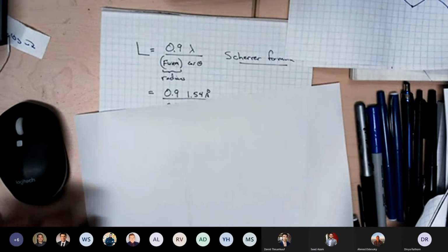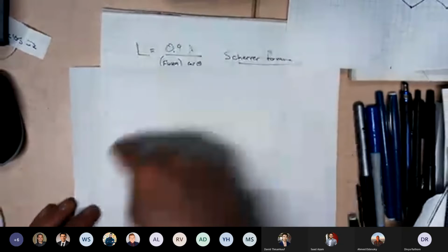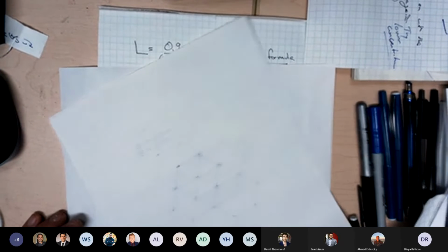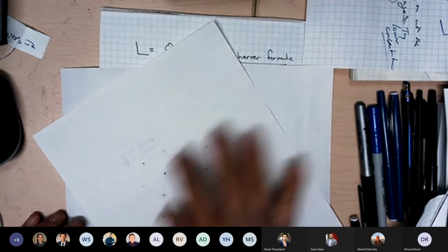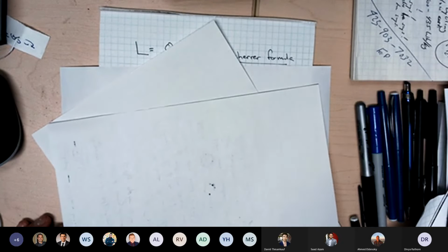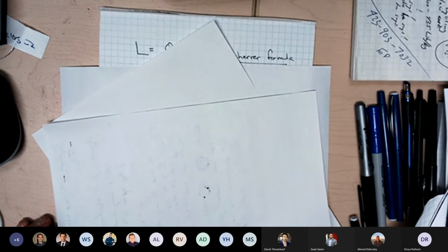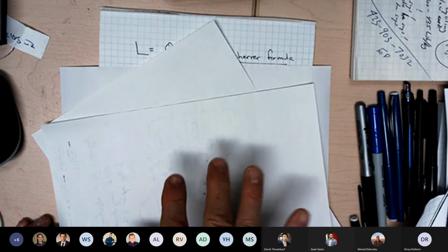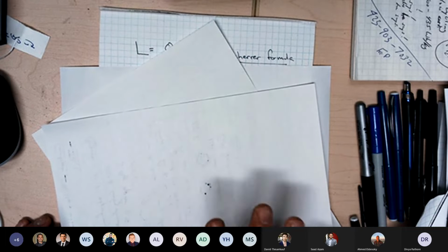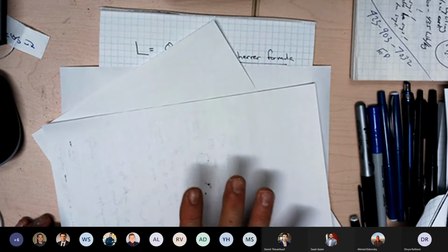So here is a graphene sheet. It has a large lateral extent. If the next graphene sheet is turbostratically misaligned and also with a large lateral extent, and the next graphene sheet is also turbostratically misaligned and also with a large lateral extent, and so on. If they're all turbostratically misaligned, you get a two-dimensional diffraction peak.